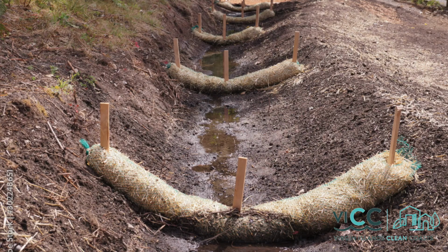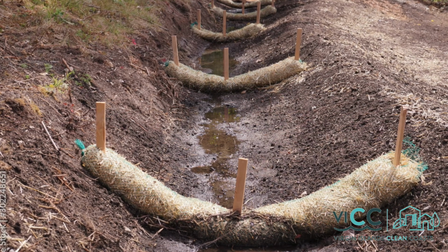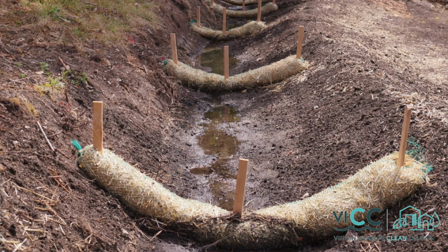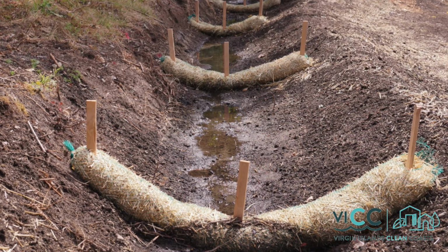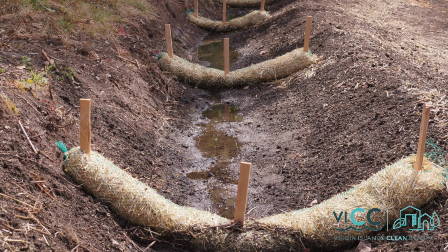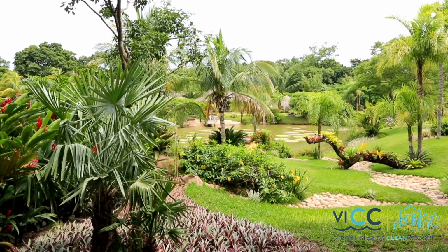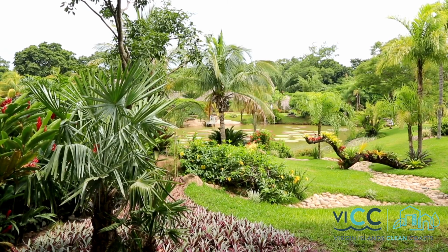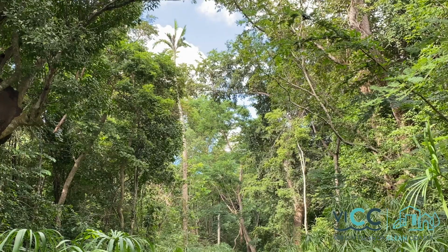Another way to slow it down is to use check dams. Check dams are small walls built into trenches or swales for this purpose. They are frequently made of rock or soil, but other materials are also used. Water pools in one section of the swale and then overflows into the next. Plant native wetland plants into these swales to create a bioswale. It's amazing how much water plants can absorb.